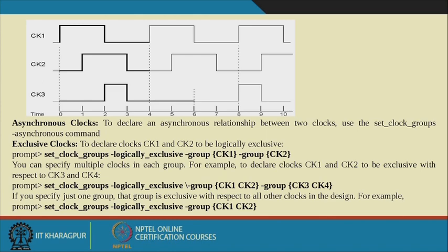And how you can set whether the clocks are exclusive or not: set_clock_groups -logically_exclusive with the group of clock 1 and clock 2. Then asynchronous clocks also you can set by set_clock_groups -asynchronous.